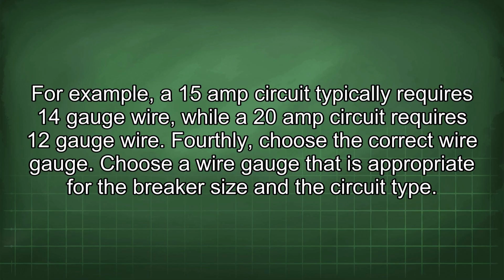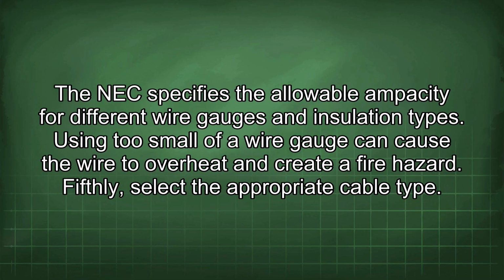Fourthly, choose the correct wire gauge. Choose a wire gauge that is appropriate for the breaker size and the circuit type. The NEC specifies the allowable ampacity for different wire gauges and insulation types. Using too small of a wire gauge can cause the wire to overheat and create a fire hazard.